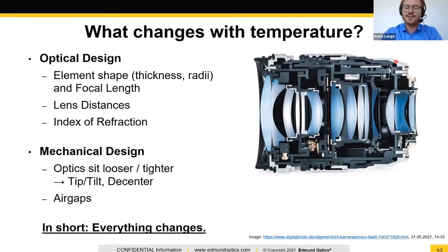But also the other way around, if you decrease temperature, it's quite critical. If your bore gaps are very small and your temperature gets low, then there's an increased pressure on your optical components, and it is not unheard of that this pressure goes to a level where your single element inside your lens just breaks and is damaged completely. So that definitely can happen.